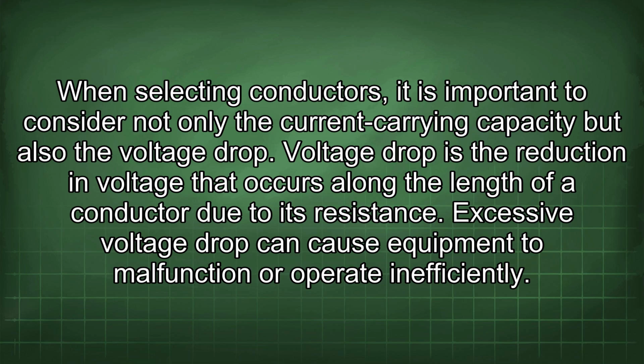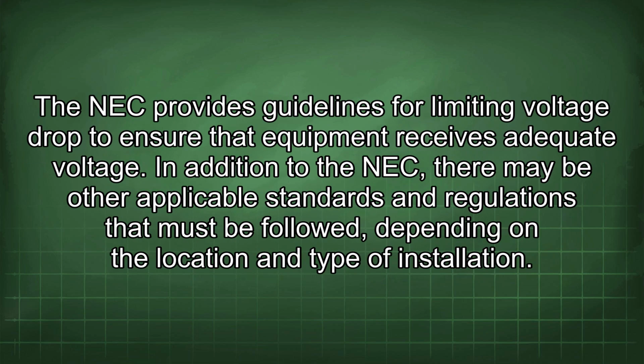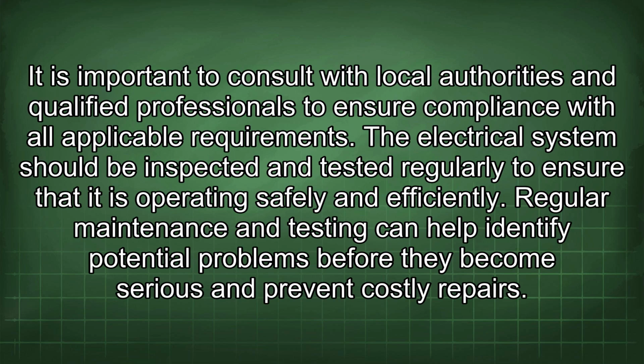When selecting conductors, it is important to consider not only the current carrying capacity but also the voltage drop. Voltage drop is the reduction in voltage that occurs along the length of a conductor due to its resistance. Excessive voltage drop can cause equipment to malfunction or operate inefficiently. The NEC provides guidelines for limiting voltage drop to ensure that equipment receives adequate voltage. In addition to the NEC, there may be other applicable standards and regulations that must be followed, depending on the location and type of installation. It is important to consult with local authorities and qualified professionals to ensure compliance with all applicable requirements.